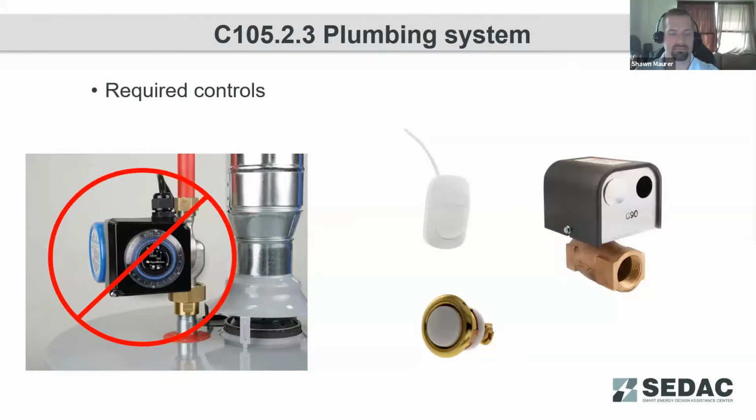That way, as the tank has hot water drawn out on demand, cold water is drawn into the tank. That flow sensor picks that up and records that as demand for hot water. That will activate your circulation loop pump. Those circulation loops will then pump until one of two conditions. If you've got a continuous circulation loop, then that pump will operate until the loop is back up to its set point temperature.